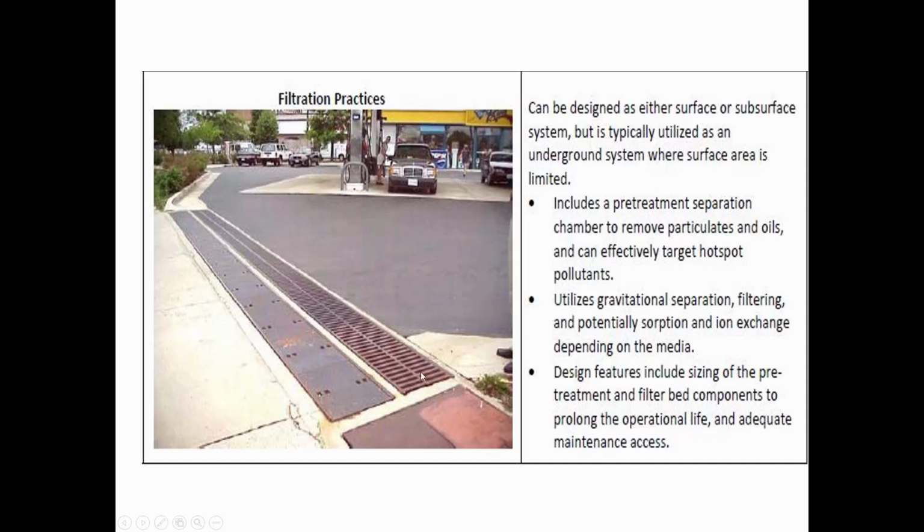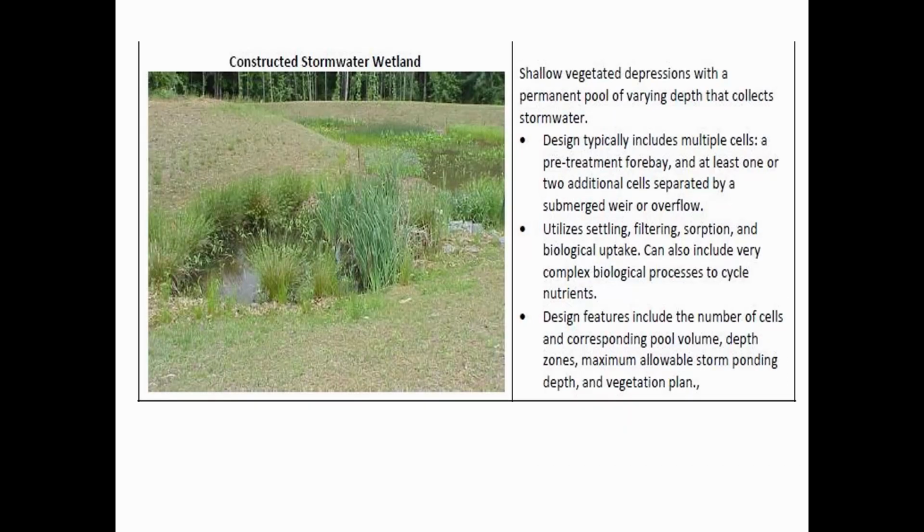And so finding ways to capture especially polluted water like that at a filling station is important. So it may be something like a passive filtration, where just by gravity you're separating oils from the top, sediments from the bottom, and maybe a separate pond where the organics can vaporize out before they get into a stream.